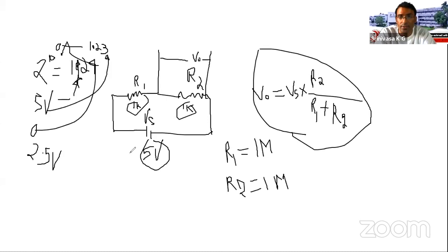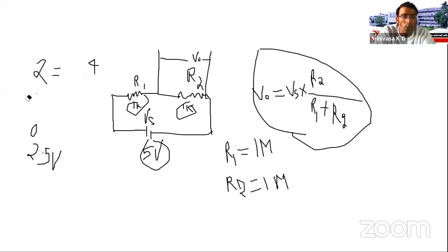512? Yes, you will get half of 1023, that will be 512. Very good. I'm going to repeat it again. You are going to use the internal ADC, which converts an analog signal into a digital format, because the microcontroller reads in digital format.